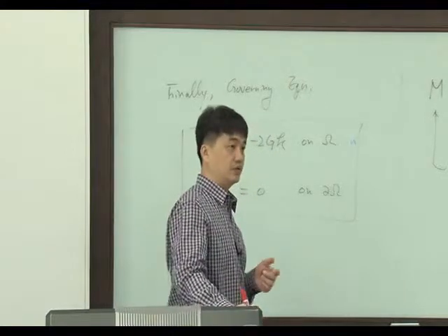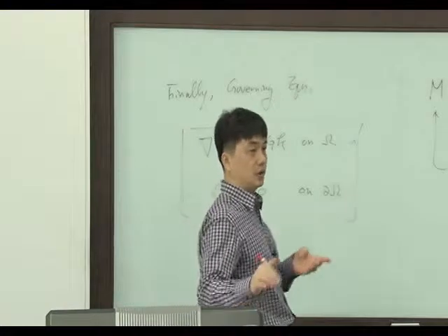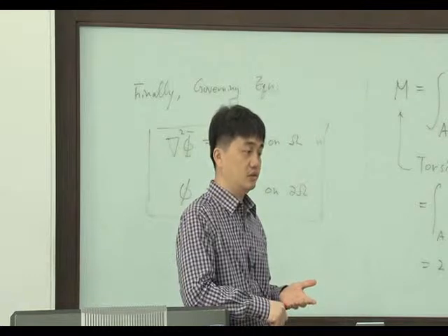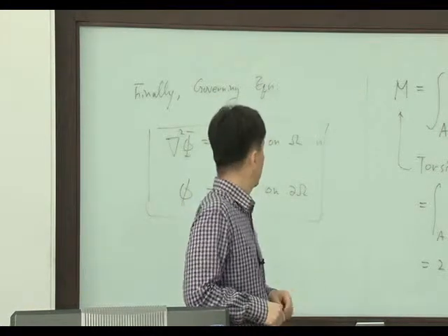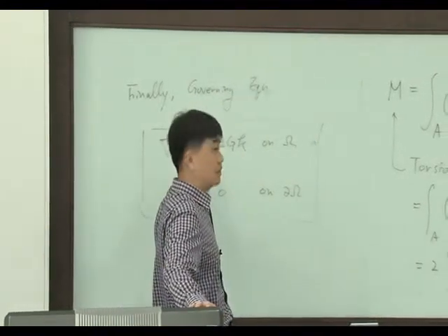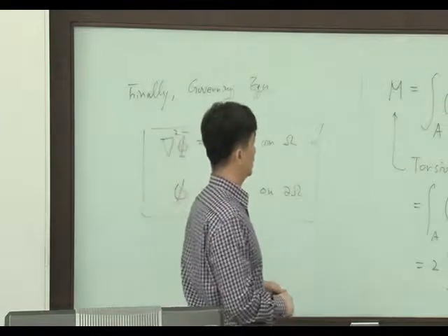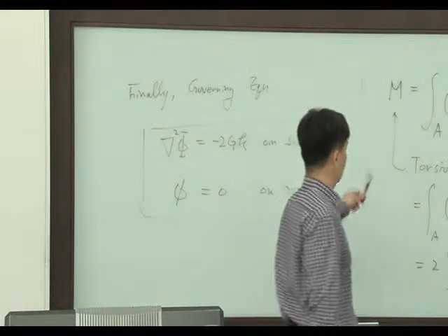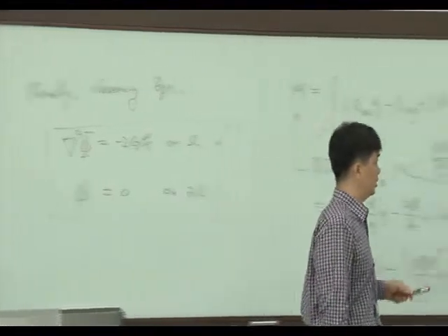So to this point, you should remember, first, we introduced a special function named the Prandtl stress function, right? Based on that special function, we rederived the governing equation. And then we calculated the torsional moment using that Prandtl stress function.